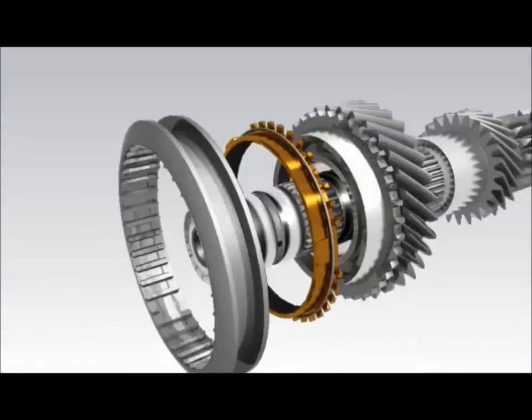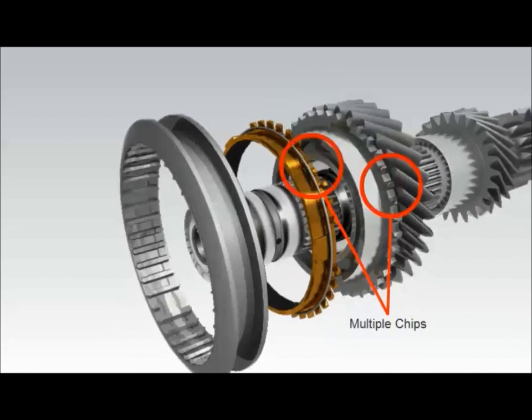Mechanical damage can also cause chipping. To identify chipping, look for asymmetrical patterns, particularly on gear or synchronizer teeth. If you see multiple chips, locate and remove the cause of the chipping and clean out any metal chips or contaminants in the engine and transmission.